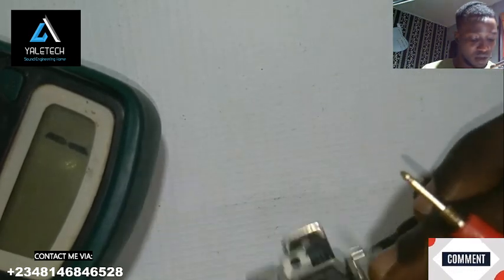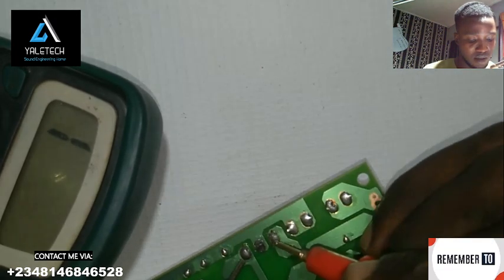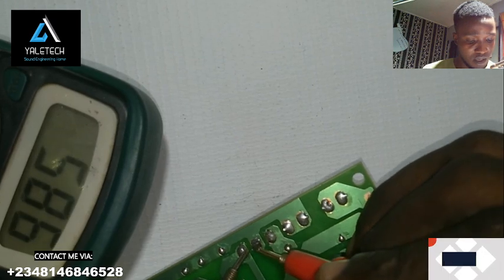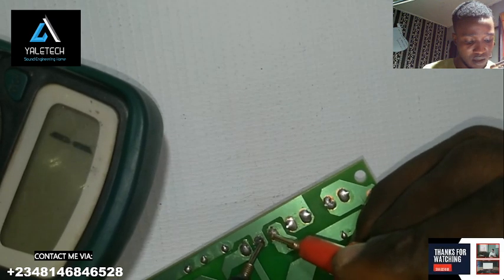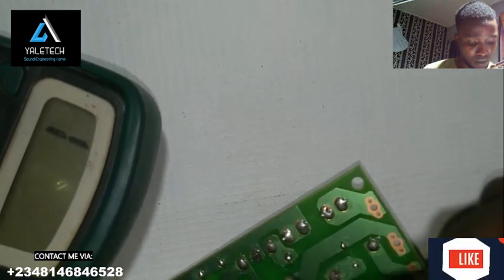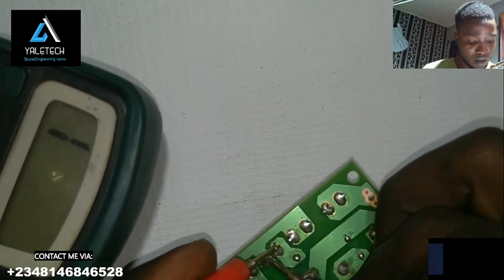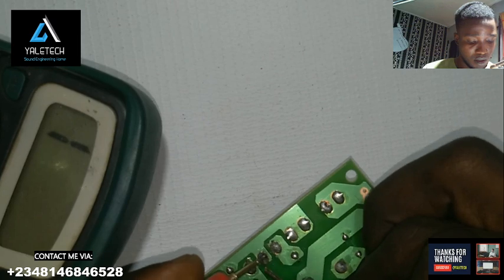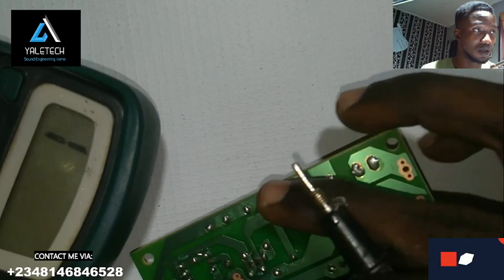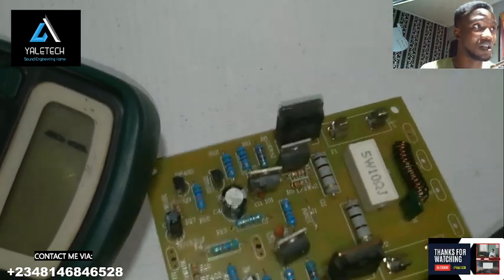So for example, now this is my A1941. Let's test this now. Look at this, reading in this direction. If I put it here, reading in this direction. I put it here, no reading. It's a good one. Reading here, but let's invert. No reading, no reading, no reading, but reading. So this one really still performs well. You understand? It's not deceptive, although the surrounding components are what will determine how it behaves.